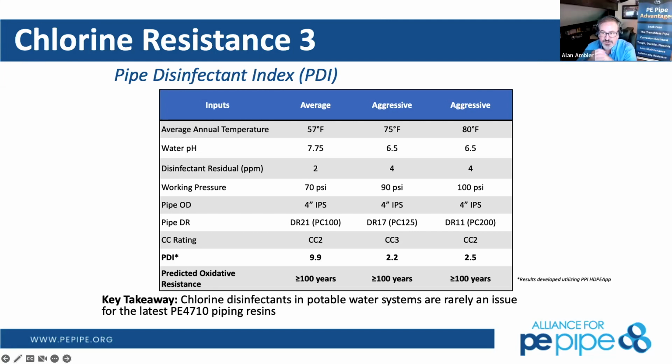Absolutely. Just to summarize straight back to the beginning that you mentioned, Matt. When the municipality uses the EPA established maximum and minimum, you have absolutely no degradation to the HDPE itself. When we want to use the equations, that's when we're getting out of that maximum minimum for whatever your use is. And remember, some of these equations were not necessarily developed for the municipal potable water industry. They are for other industrial applications as well that drive some of that.